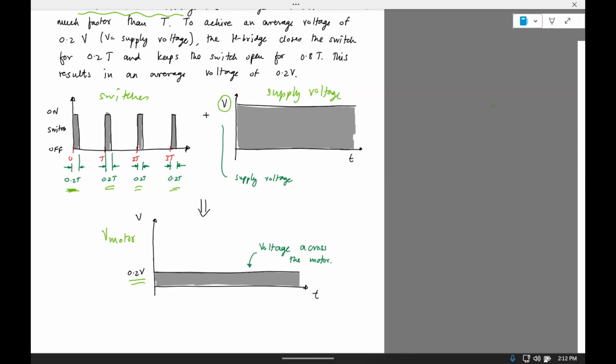And that's pretty much what the H bridge does. Now, you need a circuit for that because there are high frequency components, and it's really hard to build this by hand. You can create an H bridge yourself, but it just is not worth it. For $5, you can buy something which will do this for you, and you probably don't want to spend time making one. So this is the basic fundamental way in which an H bridge works to control the direction and speed of the motor.